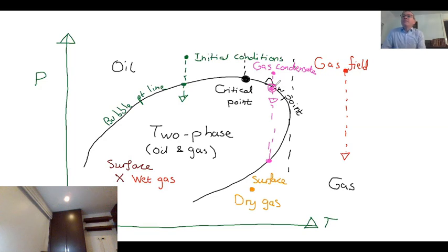So plan B is, funny enough, you want to avoid this region, but if you were to go down to this pressure, you'd still be single phase, you'd be all gas. So plan B is suddenly you drop the pressure an enormous amount, right? You try pumping more and more rapidly, reduce the pressure at the wellbore, so that near the wellbore, you're in the single phase region. Now, as you can see in this diagram, that requires a huge pressure drop, and then there's not much pressure drop to drive the fluid to the surface. Okay, so this may not be that valuable, but if you were, say, at this point in the phase diagram, right, where you're just in the two-phase region, this may be something that you would consider.